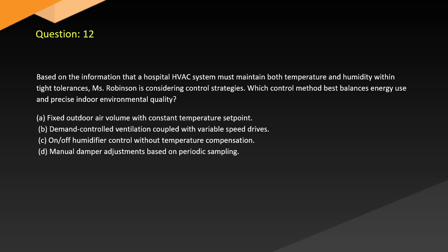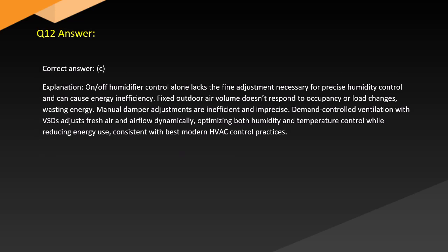C. On-off humidifier control without temperature compensation. D. Manual damper adjustments based on periodic sampling. Answer. Correct answer. C. Explanation. On-off humidifier control alone lacks the fine adjustment necessary for precise humidity control and can cause energy inefficiency.